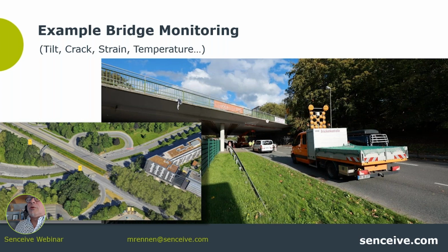And in a reinforced concrete structure, cracks always mean that there's water ingress. Water ingress causes corrosion on the reinforcement and the pre-stressing cables there. And when a steel cable starts corroding, then the diameter is reduced, and then the stress it can hold reduces, and that leads relatively fast to a decrease in stability.